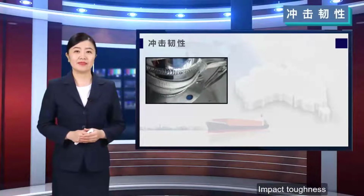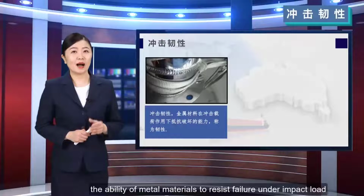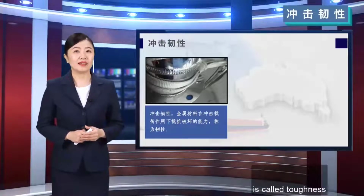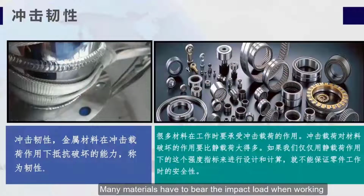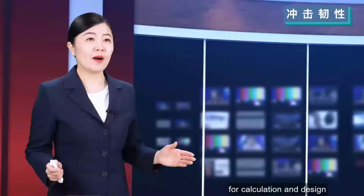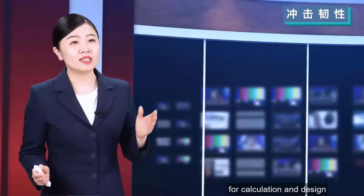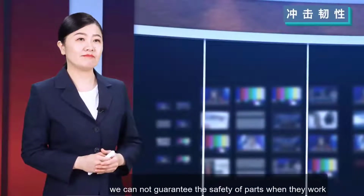Impact toughness. The ability of metal materials to resist failure under impact load is called toughness. Many materials have to bear the impact load when working. The effect of impact load on material damage is much greater than that of static load. If we only use the strength index under static load for calculation and design, we cannot guarantee the safety of parts when they work.